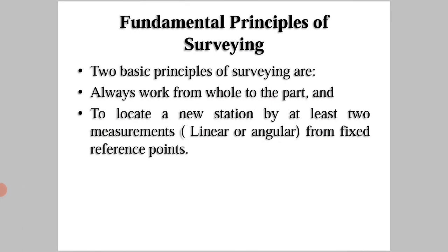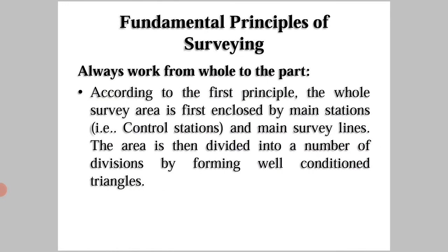So the next point is the fundamental principles of surveying. The first principle is always work from the whole to the part, and the second is to locate a new station by at least two measurements, that is linear or angular, from a fixed reference point. The first principle is always work from the whole to the part.